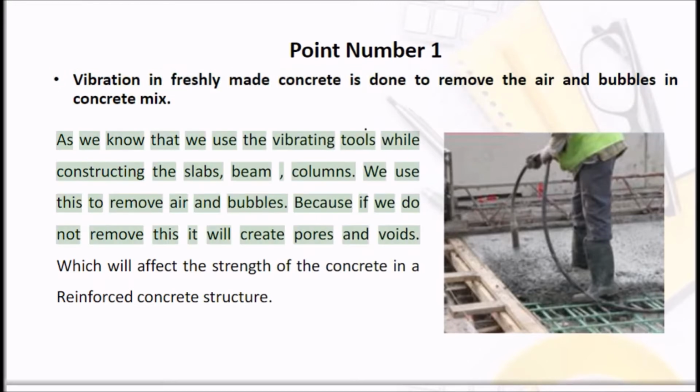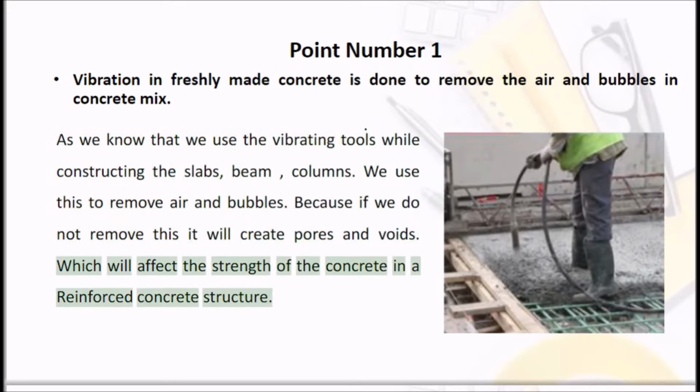As we know, we use vibrating tools while constructing slabs, beams, and columns. We use this to remove air and bubbles, because if we do not remove them, they will create pores and voids, which will affect the strength of the concrete in a reinforced concrete structure.